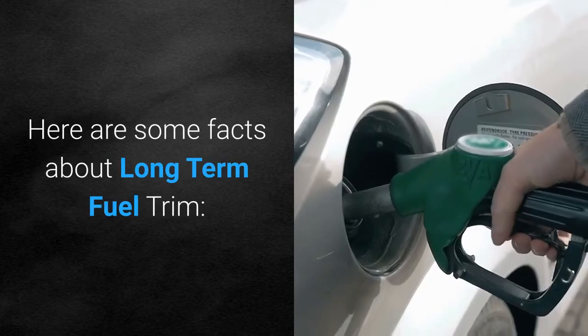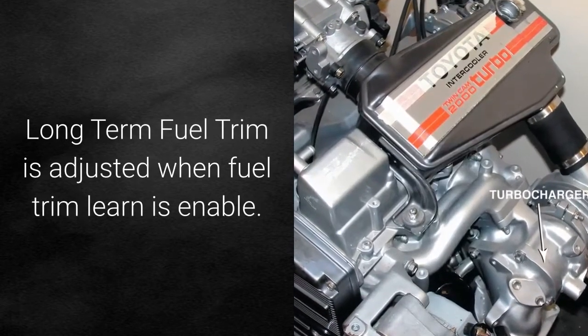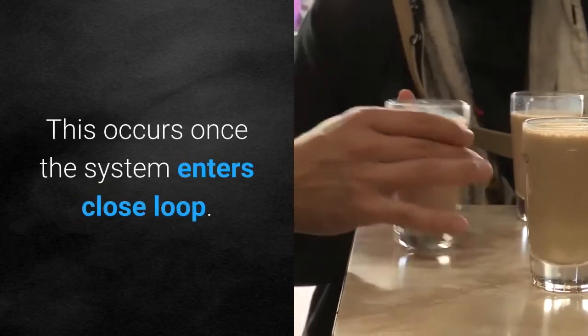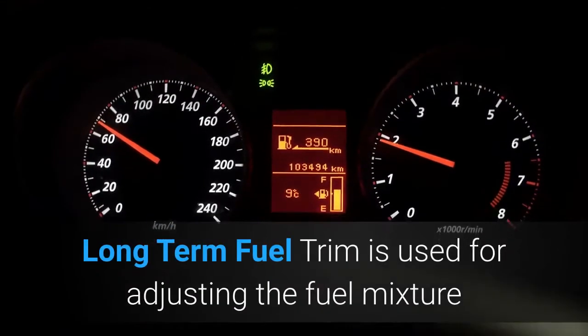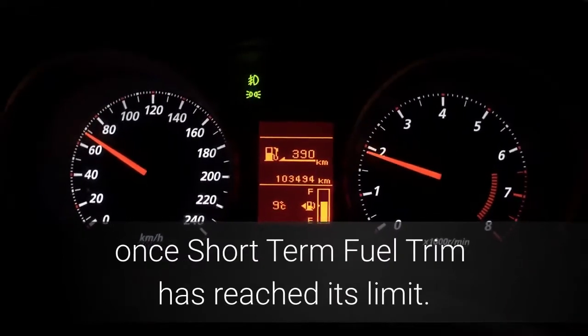Here are some facts about long-term fuel trim. Long-term fuel trim is adjusted when fuel trim learn is enabled. This occurs once the system enters closed loop. Long-term fuel trim is used for adjusting the fuel mixture once short-term fuel trim has reached its limit.